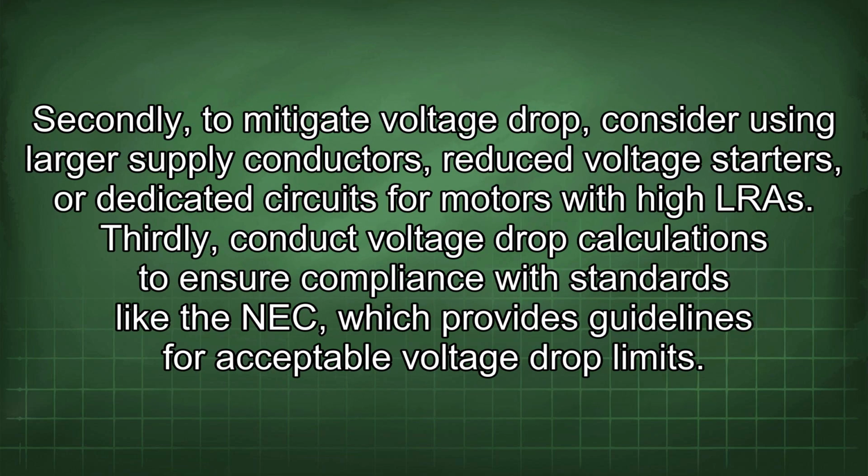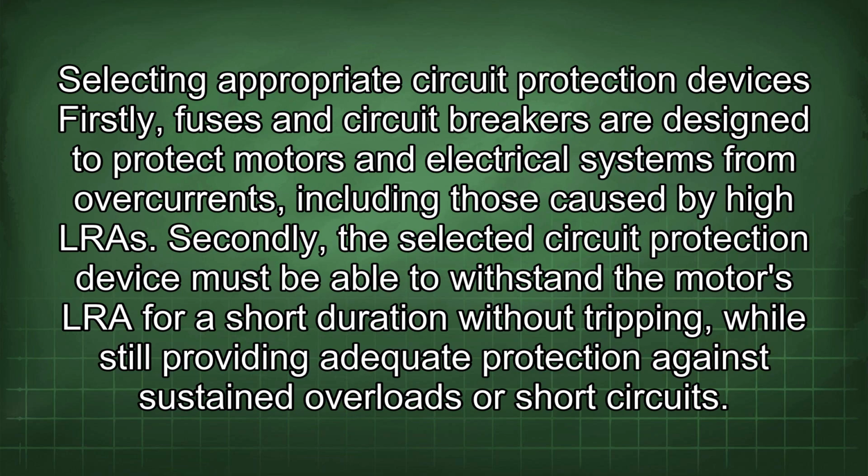Secondly, to mitigate voltage drop, consider using larger supply conductors, reduced voltage starters, or dedicated circuits for motors with high LRA. Thirdly, conduct voltage drop calculations to ensure compliance with standards like the NEC, which provides guidelines for acceptable voltage drop limits. Selecting appropriate circuit protection devices.